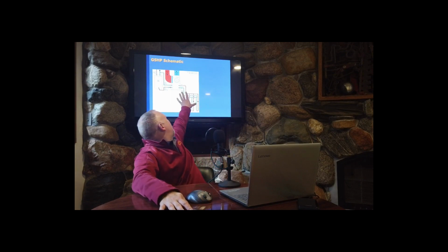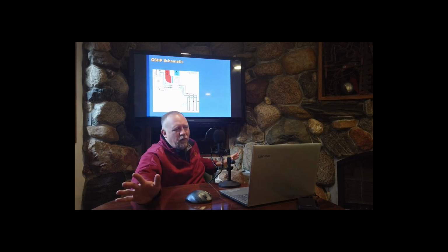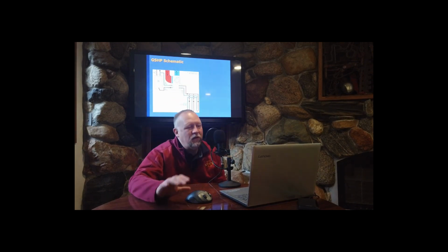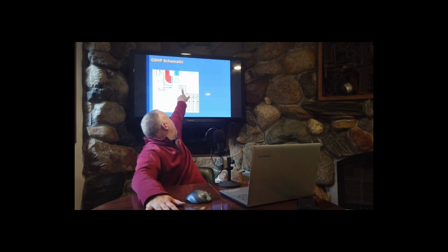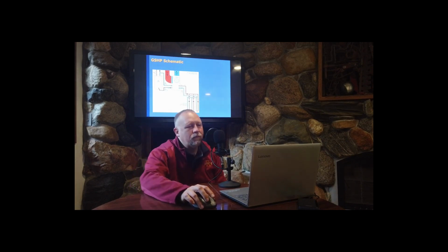So, once again, here's another schematic. I've got a fan in that heat pump. I have ductwork, just like with a normal furnace. All right, return ductwork, a coil, and supply air duct. No furnace in there, so there's no gas being set on fire, that type of thing, but it's just a refrigeration cycle. All right, let's take a look at this. A pump, probably a small one on the wall, pumps water out to the ground, and we bury a bunch of tubes in the ground and it pumps it back.